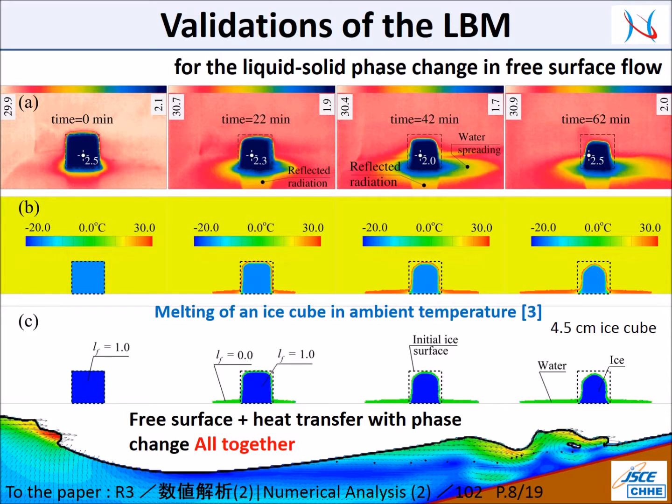We have done several experiments on liquid-solid phase transition in free surface flow. This is one example showing an ice cube melting in ambient air. The numerical result was compared to images captured by a thermal camera. After melting of 62 minutes by simulation, the result was agreeable with the experiment.